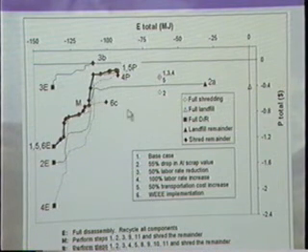Number 6 is WEEE. That's here. Okay, and then the little letters here, A, B, C, D, correspond to what you actually do under that scenario. So 6C, 6 means this is the WEEE scenario. C means the maximum profit disassembly and recovery or recycling scenario. It corresponds to letter C down here, which is performing disassembly steps 1, 4, 5, 8, and 9. You can go back to the liaison graph to get what that is, and then you shred the remainder.